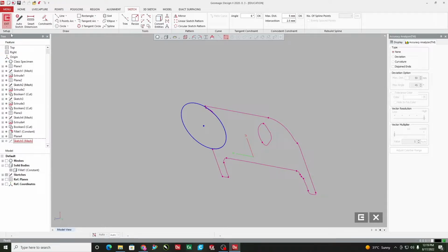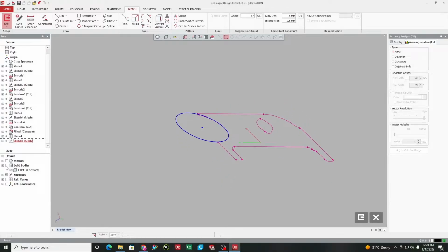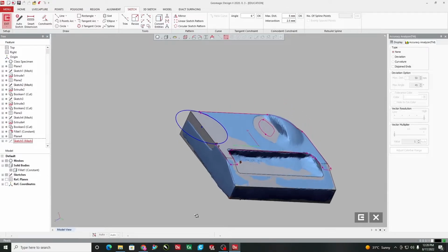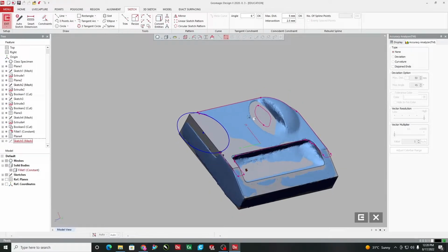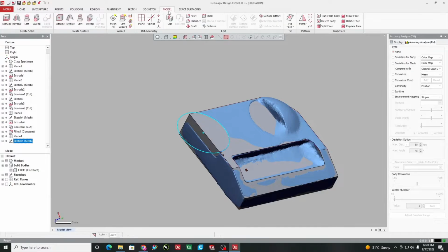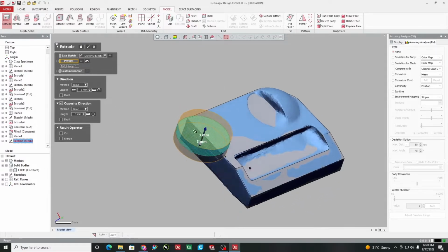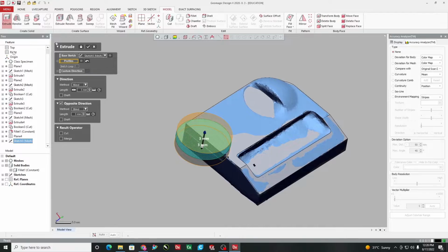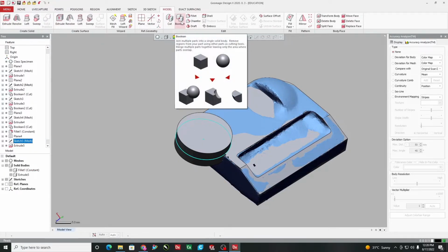Again, we will have the mesh body. We'll have the dimensions of the depth of the slot from here, where is circle slot, and we'll have the solid body. This circle will now again be used as a tool. So we'll extrude it and create a tool out of it. So I exit. Again, I come to model option. It is asking to create a tool out of it, or create a tool means I am creating another body. The depth is again 3 mm here.